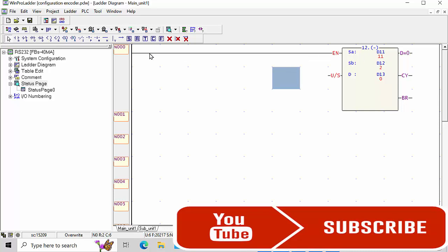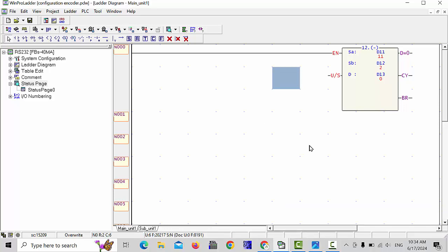You connected with analog in the field. After that, you like to make sure of the value. For example, this is the raw value coming, figures coming, bits coming: 32, 42, 62. How can you measure with this value, which you like to see on the display? This is the 10 volts or 20 volts, because an analog value runs 0 to 10 volts and 4 to 20 milliamps, and this is not basically coming as voltage, this is coming in bits,